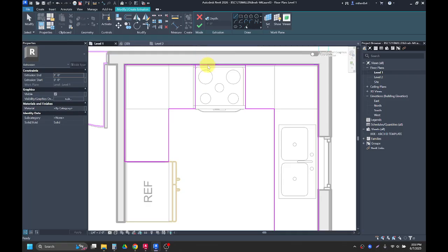So I'm going to hit escape 100 times. I'm going to slice this line in half and then make this into two. So I'll teach you a new tool then. The slice tool is keyboard shortcut SL. After we've hit escape 100 times, SL, and then your cursor turns into a little knife, and then you can just cut it in half.